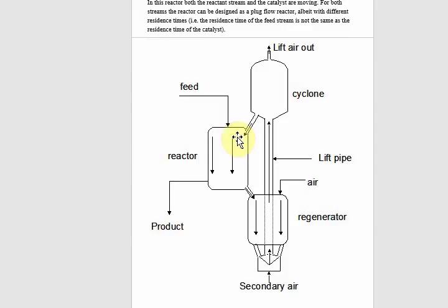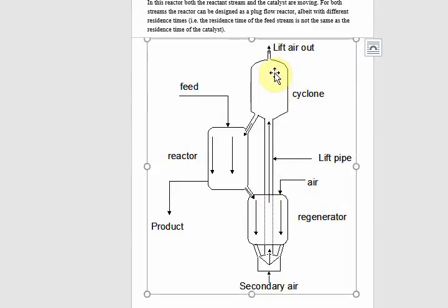So you can see here's a catalyst regeneration loop, right? Fresh catalyst in here, then the catalyst as it's reacting gets coked, and then the coked particles are here, where the air is blasting it back up and burning off the coke as it does so, and then we've got the refreshed catalyst falling back in again. That's quite continuous. The way I'm describing it kind of implies a cohort, but of course it's not like that. While particles are falling through here, there are other particles already being lifted through here. So we have a constant flow of particles through this reactor with a constant flow of feed.